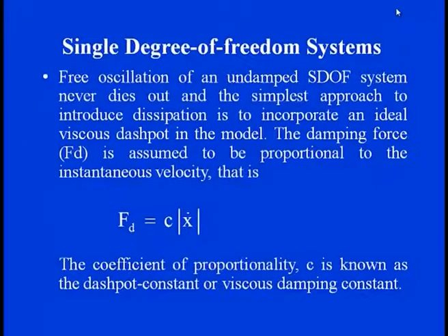The damping force, which we assume to act in one direction, is also assumed to have a linear relation with the velocity component, followed by a constant c, and this constant is a function of the viscosity of the oil in the damping device. So, these assumptions clearly show that we are only considering the damping in one direction, and that the variation of velocity according to the motion or oscillation of the object is in a linear way.